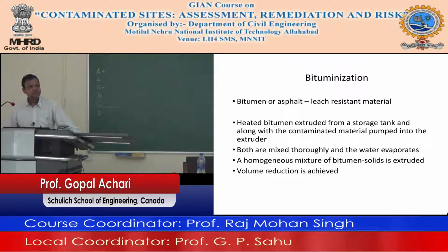So we have learned 3 of them by this time. Adsorption, in which case you use a sorbent material. We talked about sorption over the last couple of days. Emulsified asphalt is one, and you can use it for things like paint waste, because you want the hydrophobic material of the paint to separate out from the water. You mix it together, the asphalt and the organic paint just separate out, the water separates out, and you can do some minor treatment to the water and discharge it.